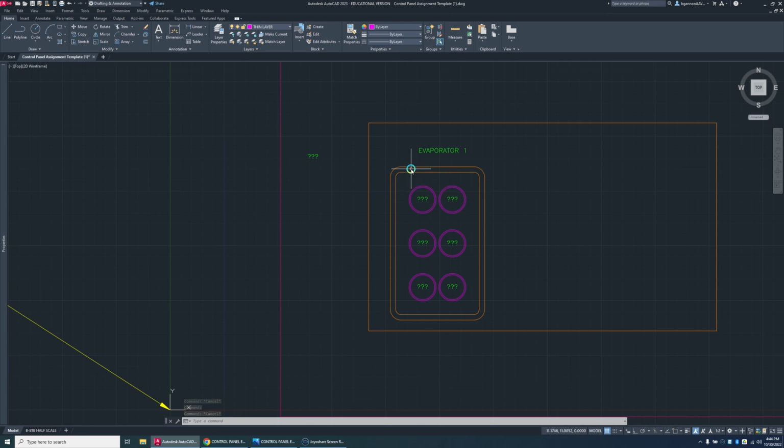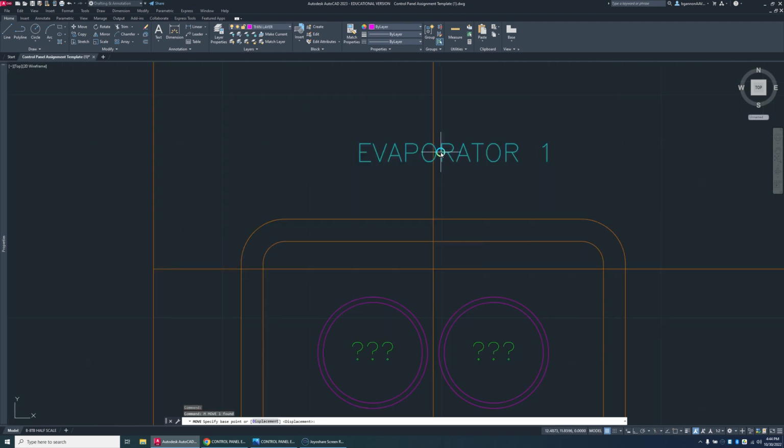So what I'm going to do here is I have a line that's coming up from the bottom. I'll offset by 6.94. We have dimensions, and I'll offset that one. That's going to be the center of this here. And then the center mark going across, I'm missing a 3.19, going down left to right. Okay. And then I'm going to move this here, and I just want to get generally in the center. I think right about right there. So generally in the center, you want to make sure it looks good. Cool. And then I can actually delete these ones. That's great.